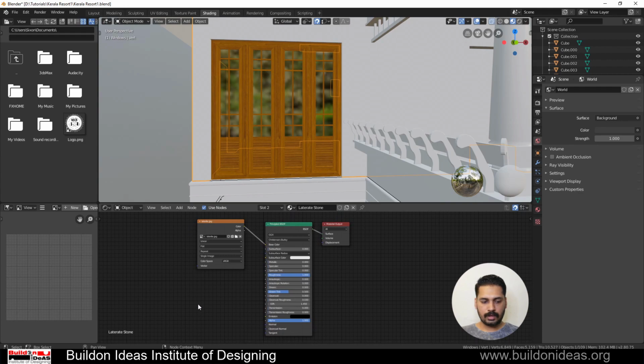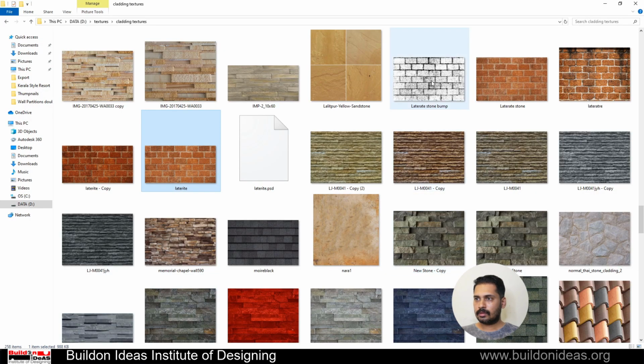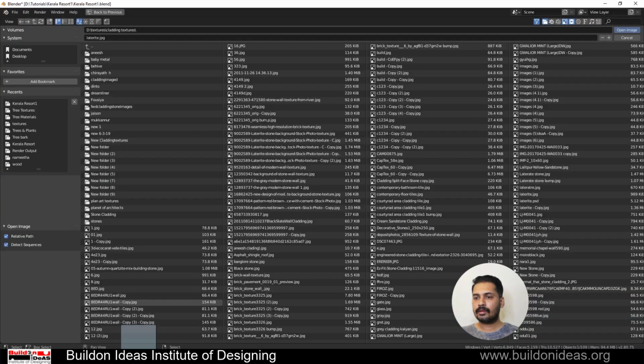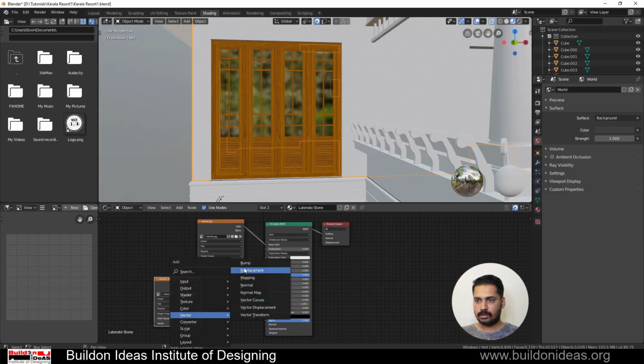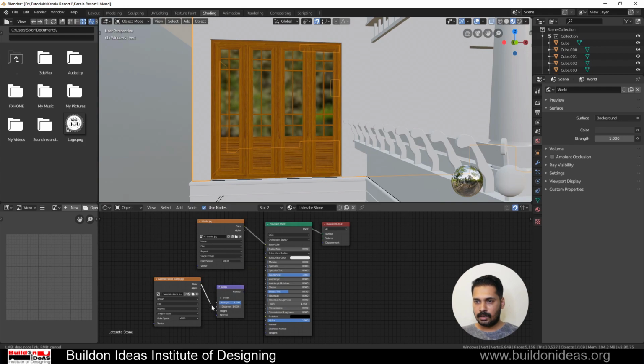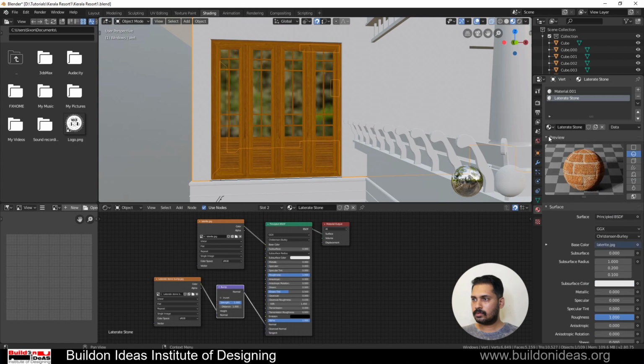and then I'm adding a normal map. So again I Shift D, and then going into this, I'll just select the map for that, and then click OK. Shift A to give a bump map, add this to the height and this to the normals. So just have to have the preview. This is how it looks.